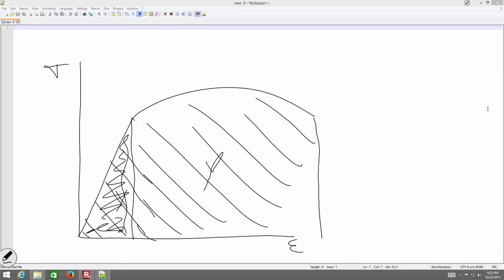Poisson's ratio is the ratio of the true stress to true strain, the lateral strain to axial strain, shear stress to shear strain. Actually, it is lateral strain to the axial strain. Most engineering work is based on engineering stress and strain rather than true stress and strain because engineering stress and strain is easier to use. Design using ductile materials is limited to the elastic region where there is little difference. Reduction of cross-sectional area of parts at their service stress is well known due to Poisson's ratio, but it is needlessly complicated.